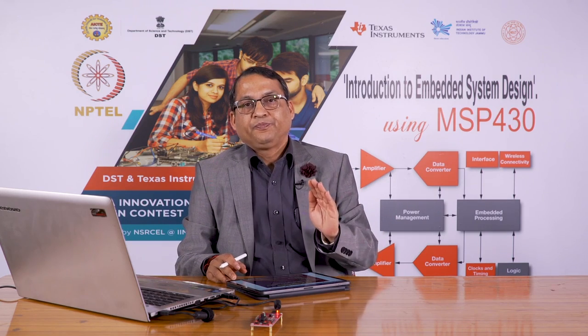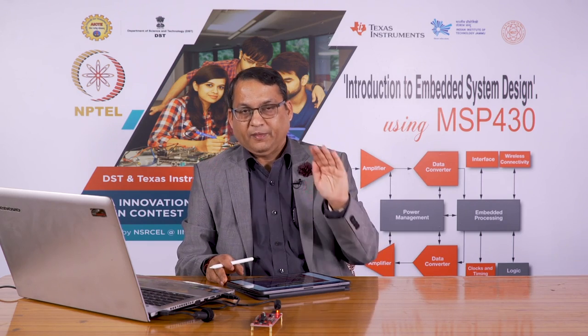So, you do not have to worry. The only thing you have to do is decide whether you want the port to become input or output by writing into the direction register, and if you have chosen them to become output, write values into the output register, and that is it.